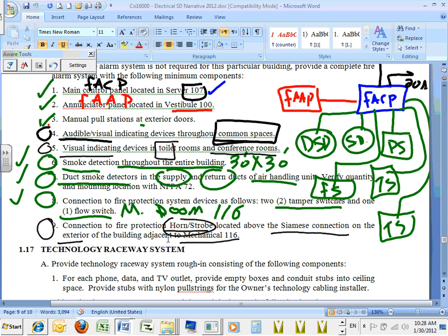Now you're going to be able to see both of them, guys. So you're going to be working in two levels. One level, floor plan system, put anything that's in a wall there. Anything in the ceiling, please go to the ceiling view light. Don't create another ceiling view light, and put them there. And then they will show up in the floor plan system. Okay? That's Revit talk.